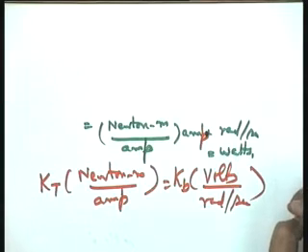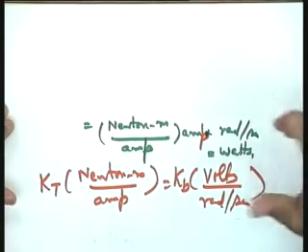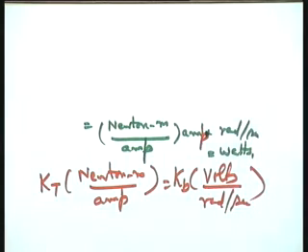It is a very important result in the sense that if you are modeling a motor experimentally, you can visualize this situation. Conducting an experiment to measure kB is much easier and more accurate than that to measure kT. You can think what type of experimental setup will be required to measure kB. It is so simple.